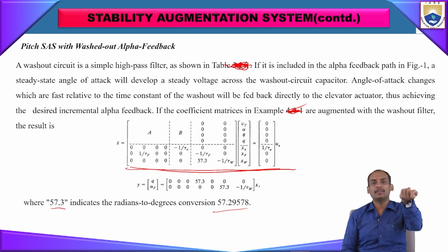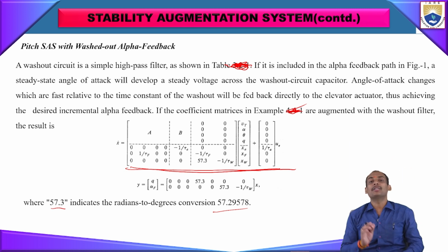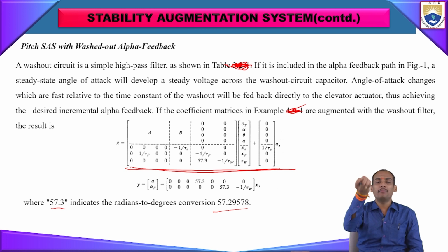So here it is showing that this transfer function is like an integrator function only. This function also depends on the summing amplifier voltage, and the signal that comes from the controlling stick, how much signal is coming out. So this depends upon the signal coming from the pilot, and the transfer function output values also. So we cannot shape this transfer function for our benefit.